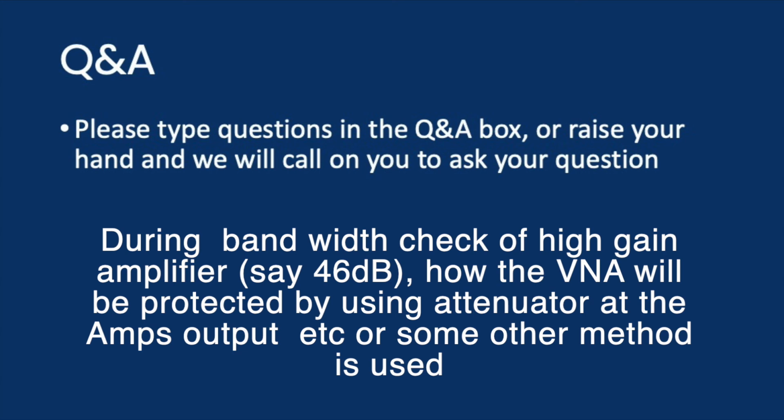Okay, yeah, that's a good question. It doesn't matter so much the gain of the amplifier, it's more how much output power that amplifier provides. Our VNAs have a port threshold of pain of officially half a watt, but you can go up to about plus 30 dBm. Of course, even at those levels, I say threshold of pain, that's before you're actually damaging the device. But long before that, you're starting to get into regions of internal receiver compression, things like that.